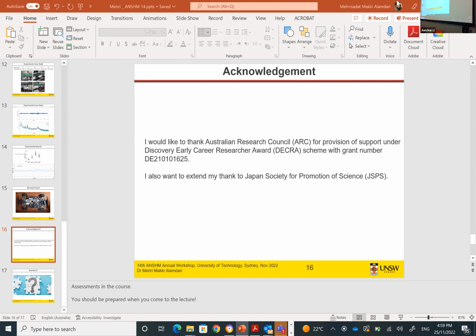All right, thank you, Mehri, for the great presentation. I'm just curious if you have any plan to implement model-based methods for the detection, because from what I can see, you can actually get the mode shape from your measurement. When you move the vehicle along the bridge, you get the data at each point of the bridge. So it would be possible to get the mode shape of the bridge. So maybe that would be a feature to consider in future.